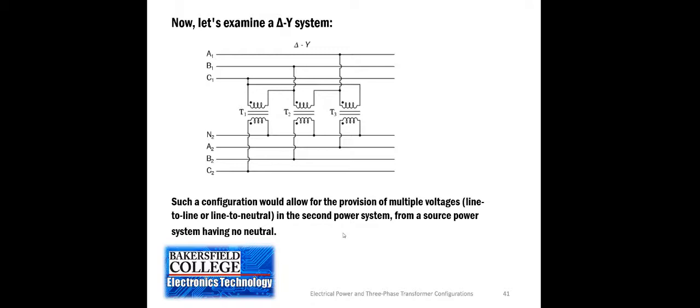On the delta configuration, you see that you have one side of the transformer going to one of the lines, the other side of the transformer going to the second one in series, and also to a second line. And then that second transformer goes to the third transformer in series and connects to yet another line, and then the first one starts at the opposite line.